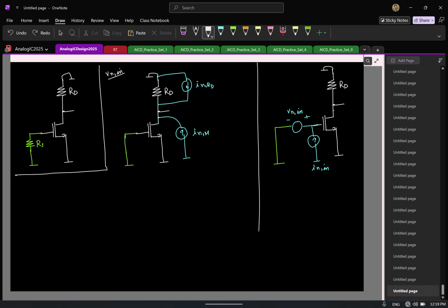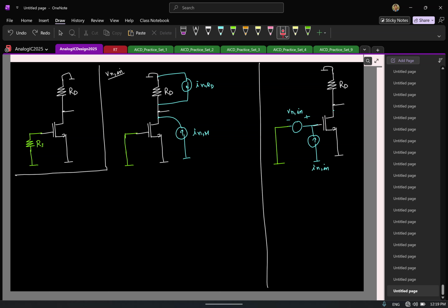Again, the job is simple. In the circuit here, you find the output noise power spectral density, and then find the gain from the input to the output. The output quantity divided by the gain squared gives the input quantity. That's all. You can either find the noise in the output voltage, but in most circuits, it's easy to find the short circuit current. I'll define this as my output quantity, because finally I'm referring everything back to the input. Whether it's voltage or current will not make any difference. You can choose depending on which will be easier. Here you will see current will be easier, because can you directly tell me what is my Iout?